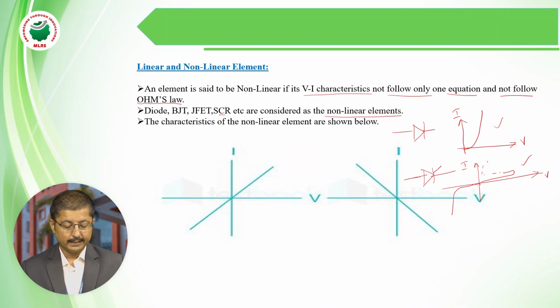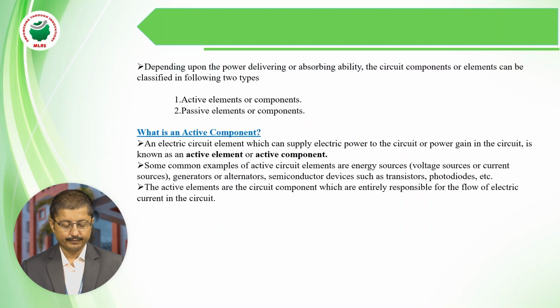So that is about linear and non-linear. Linear elements follow Ohm's law, their equations pass through the origin, and the VI characteristics are linear. Here the VI characteristics are non-linear and do not follow Ohm's law, so we say it is a non-linear element.